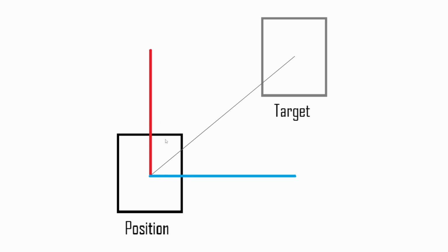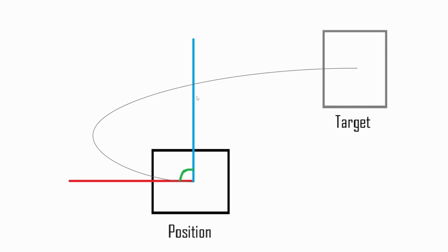This is very nice. But the problem is, as soon as you add in a heading error like this, then what your deltas are going to be from the robot's perspective, the robot's not going to know how to deal with that. So what's going to happen in something like this is, assuming this is at 0 degrees, that's a big assumption, your heading is going to take a while to catch up, and eventually it will, but you don't want this curve unless you're going for that. But don't do it this way, please don't.